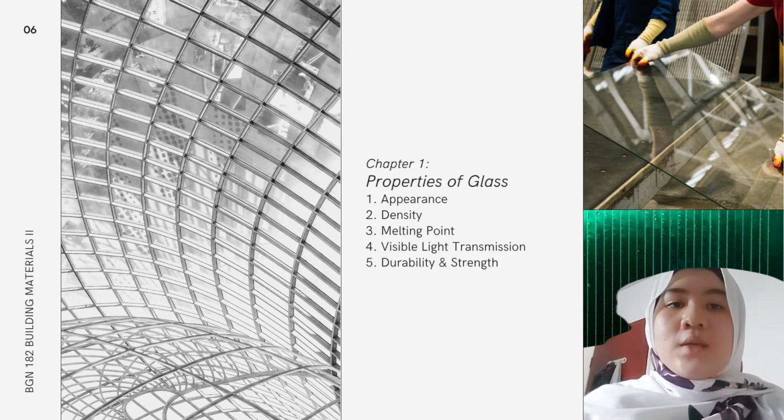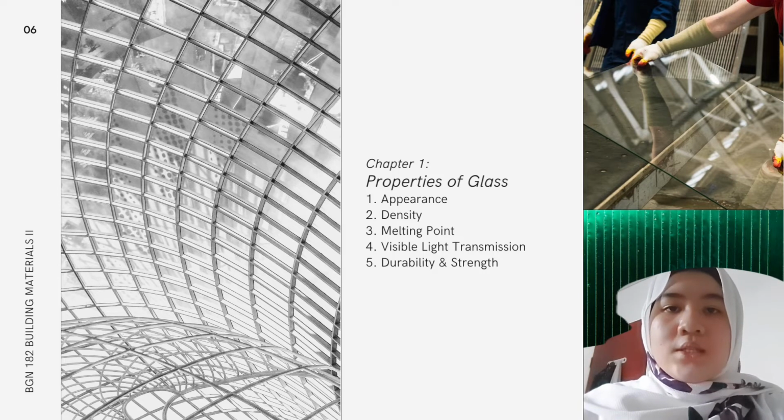Glass in a building is required to resist loads such as wind load, impact by persons and animals, and sometimes thermal and other stresses. Resistance to shock loads is about twice that to static loads. Patterns and wire will reduce the strength. Thermal movement is lower than the material in which the glass is normally fixed, so allowance should be made for movement.